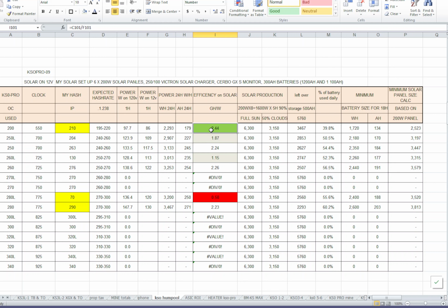Obviously the winner is the 200 gigahash stock, the most efficient firmware, because overclocks always draw more power and produce more heat. Plus with the stock, you don't even need to use the fan very much if it's a cool environment. So you can do it at probably 5 watts or something like that. I don't know. Well, let's go to the next one and run the 270L version.